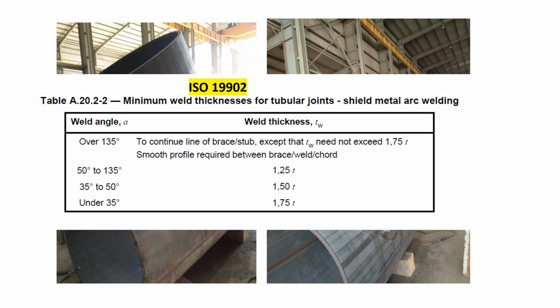This range can be called a zone. So to ensure the distribution of the weld at various locations of the node connection, it is deemed necessary to do the zone marking and specify the required weld size on different portions. For the purpose of this video, I will name them zone 1, 2, 3 and 4 sequentially.